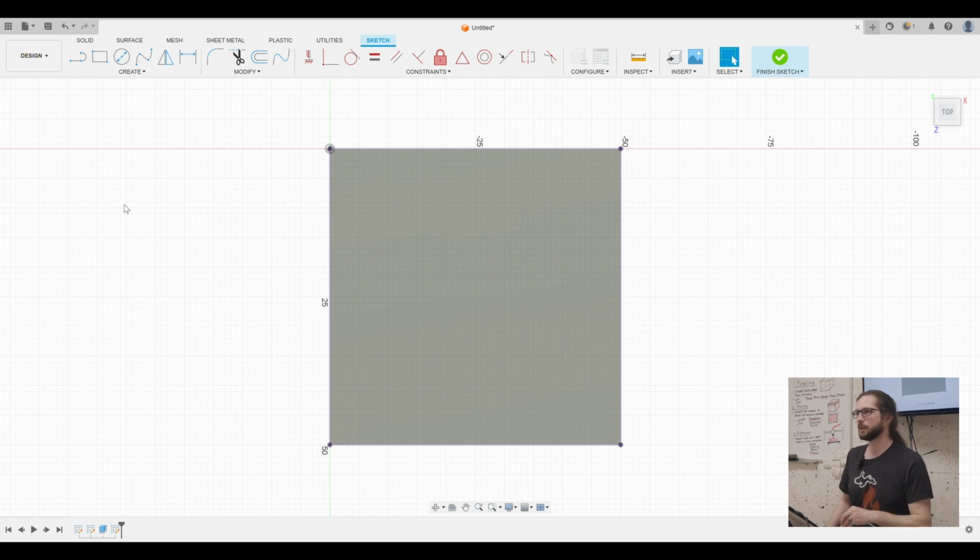There is one other way to do a projection, just because I assume that you will be thinking about this in the back of your mind. If instead of that light shining a shadow onto your drawing technique, you have a two-dimensional drawing plane that is intersecting an already existing three-dimensional object, you can also tell Fusion, tell me where the line of that intersection is and project that, and that's the intersect command.